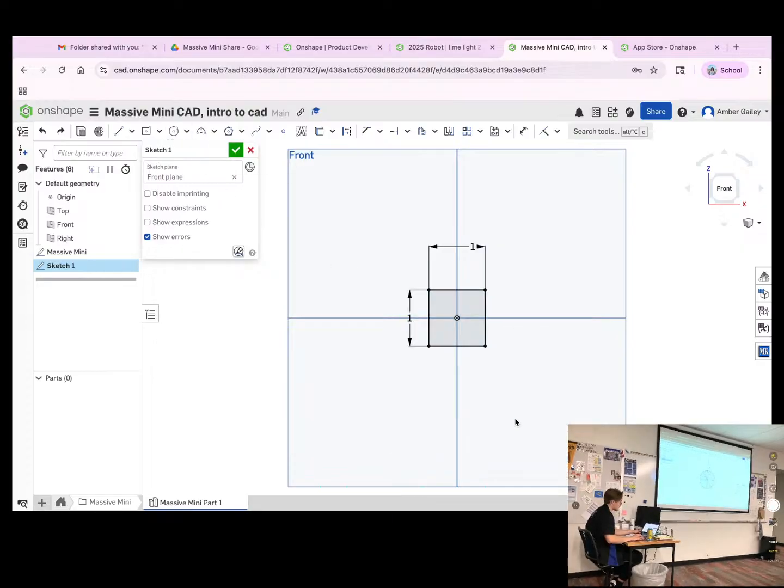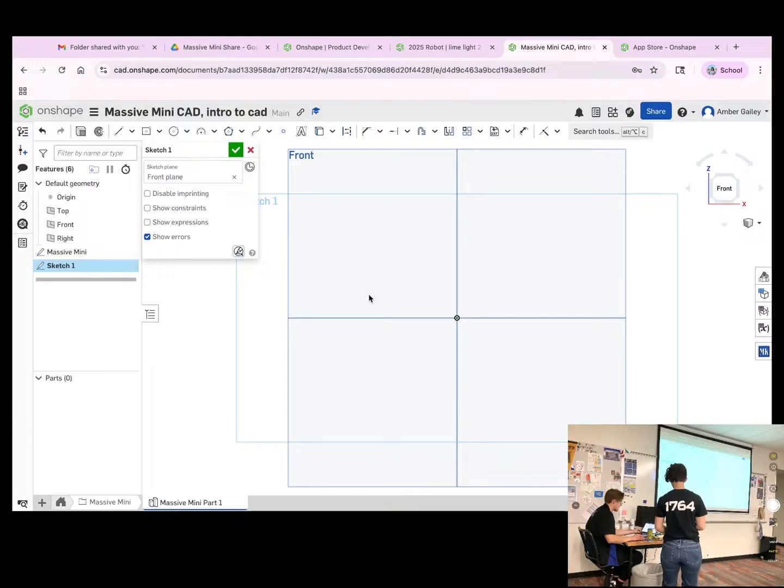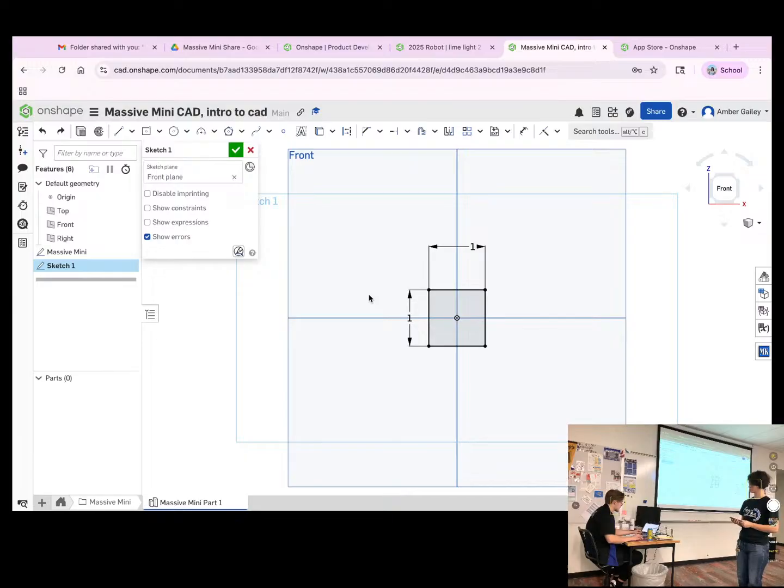Tolerances. We also had a big problem with this this year. Our elevator, we decided we wanted to make our own bearing blocks for our elevator, and we wanted our elevator to stow completely flush at the top. And we wanted the gaps between each stage to be so minuscule. It's actually a negative gap between each stage. But making sure you have those tolerances is crucial. Our belt ran between the stages, and if we had issues with our belt, say our belt was getting torn, we can't see our belt.